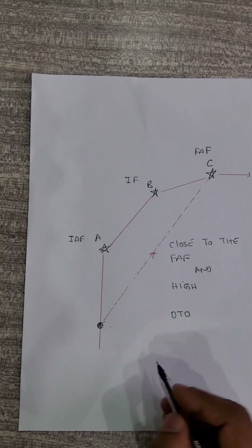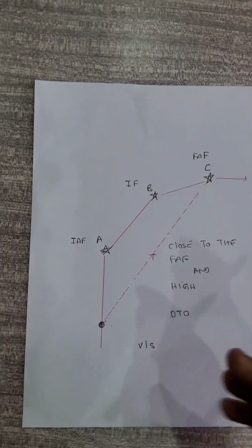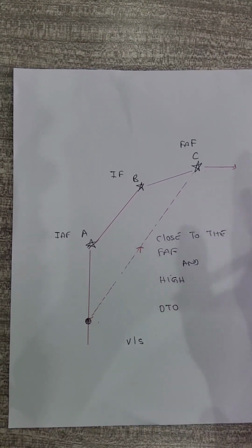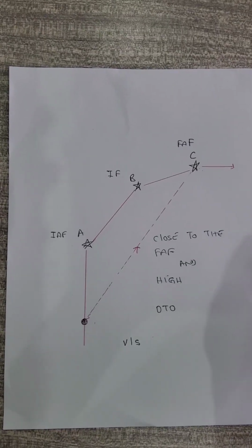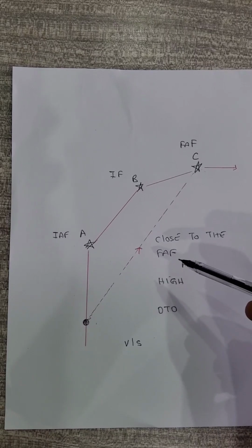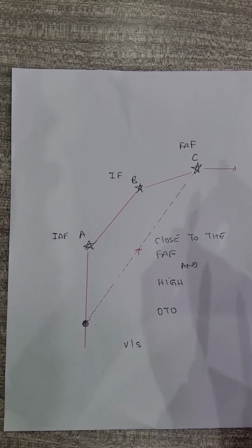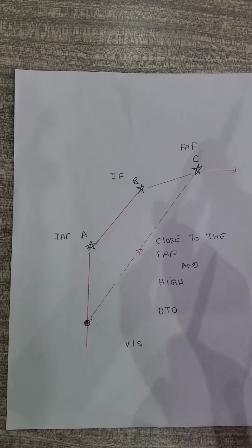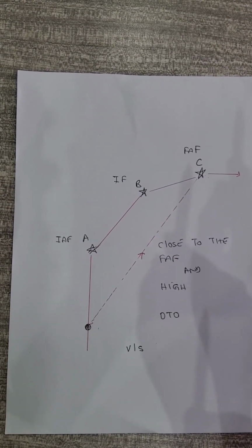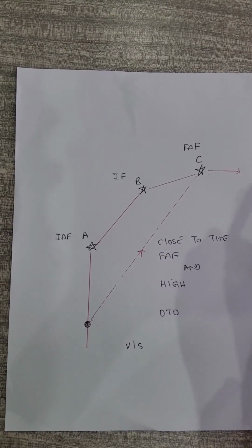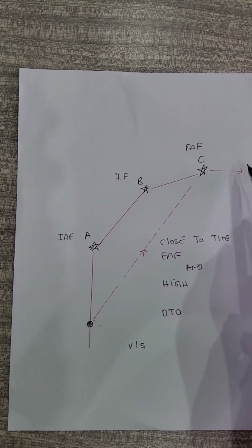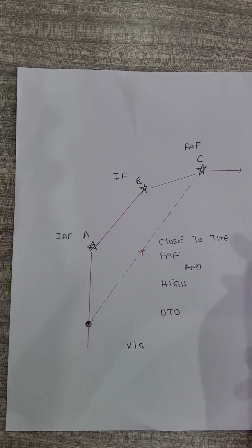Once you select vertical speed, the VNAV automatically will come with an amber message saying VNAV is disconnected. Fine. Why? Because now the FMS has been told I don't need VNAV anymore for now, I'm going vertical speed. So when we use vertical speed, what happens? We are maintaining the same vertical speed as we had with VNAV. So engaging the vertical speed will keep the aircraft on the same rate of descent while we reprogram the FMS on the new profile. I'm hoping that is making sense.